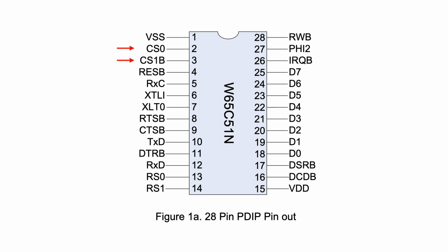Well, rather than inverting individual address lines on a device-by-device basis, maybe the memory interface could provide inverted copies of the 5 least significant bits of the address bus for any device to use for this purpose. I could do that with just a single 7404 hex inverter IC. Now we have a 3-chip memory interface, a 74138 to generate the read and write strobes, a 7404 to generate those inverted copies of A0 through A4, and either a 7400 or another 74138 to deal with the flash write strobe. But I know what you guys are thinking.